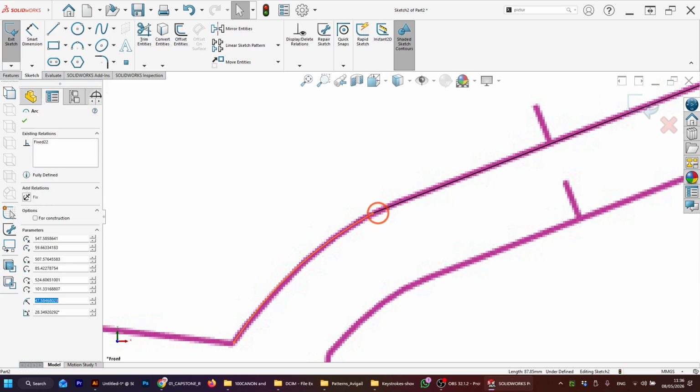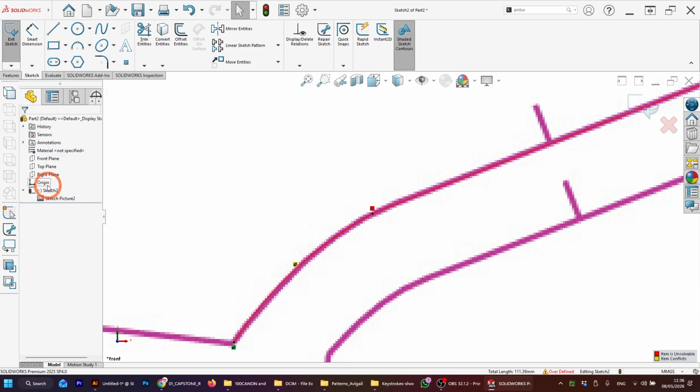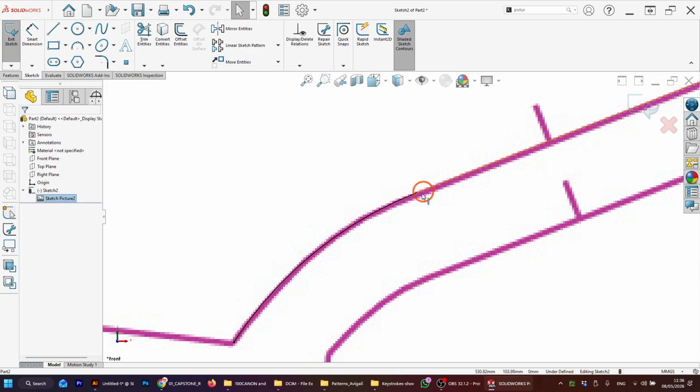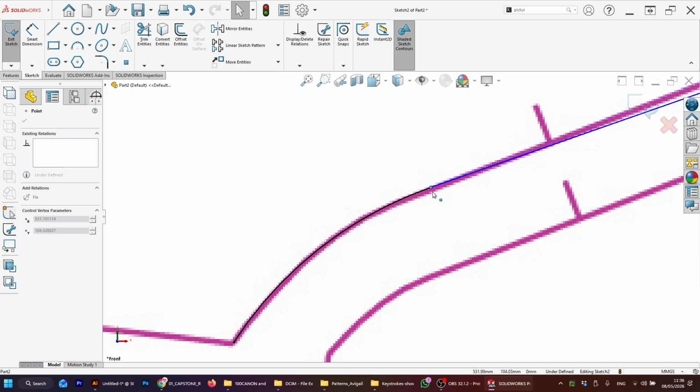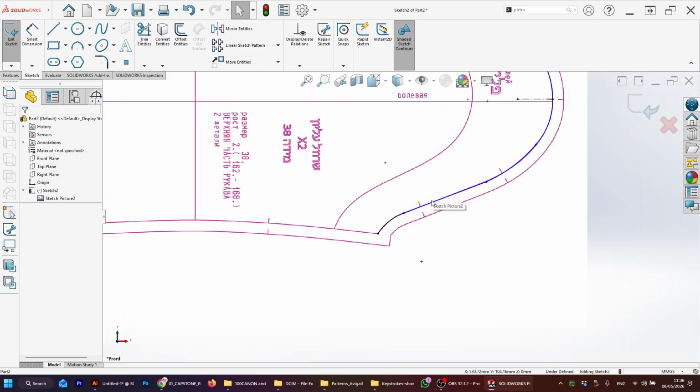Now we can ask for a tangent between these two lines. It's telling me I can't, because you locked everything. When you see red, it's saying it can't do what you ask because there are too many rules. So let's remove the fixed constraint in the rule panel. And now it's telling me that yes, it can actually do it. Maybe we locked that line a bit too soon.